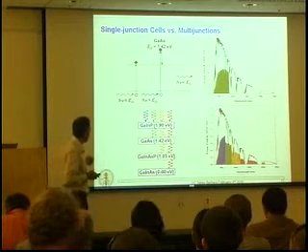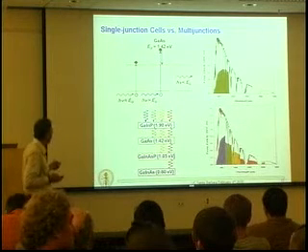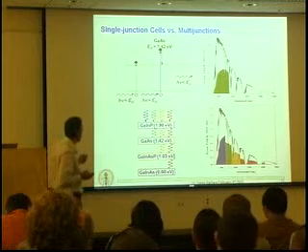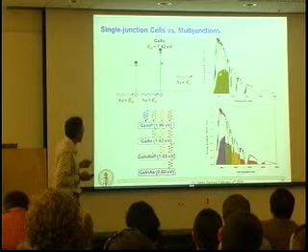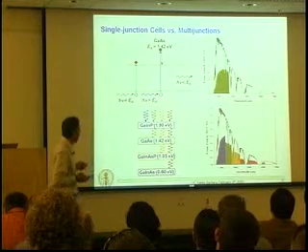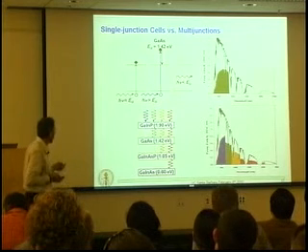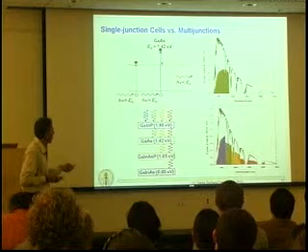It's very difficult, if not, so far it's been effectively impossible to harvest these hot photogenerated carriers before they relax to the band edges. And as a result, over here, there's a big deficit between the power density in the solar spectrum and the converted power. And of course, there's a whole spectrum below the band gap where the semiconductor is transparent that we don't absorb at all.